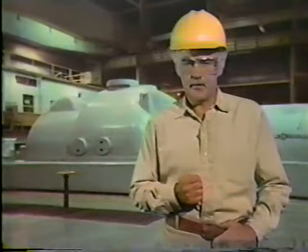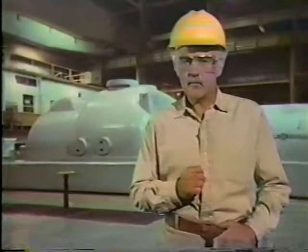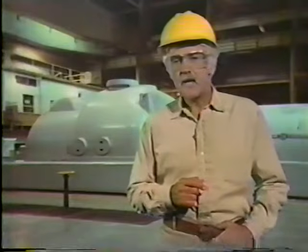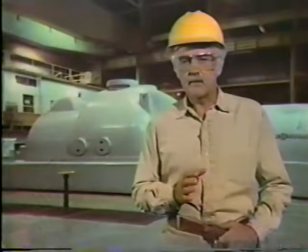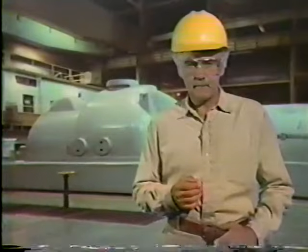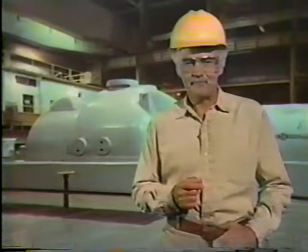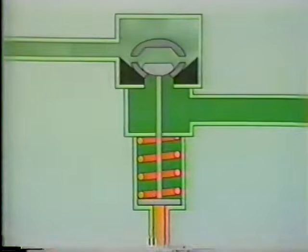Generally, there are 2 to 4 main stop valves on a turbine, and at least one performs the function of regulating flow during startup. The main stop valve that regulates flow is a little different from the valve we just looked at. So let's see how this valve is constructed, and then we'll see how it works. The valve in this illustration is similar to the one we saw earlier, except it has an internal bypass valve.